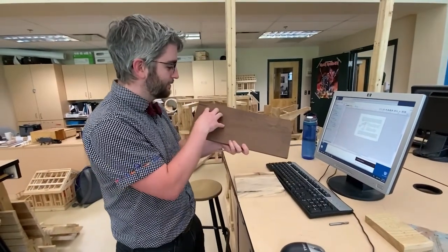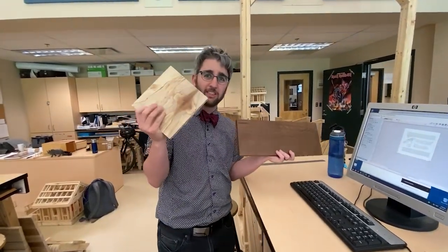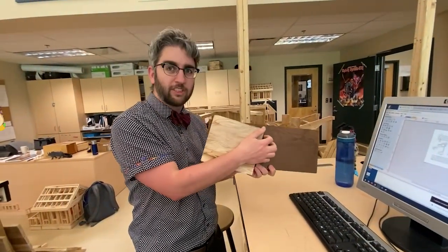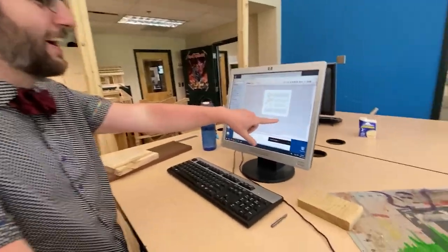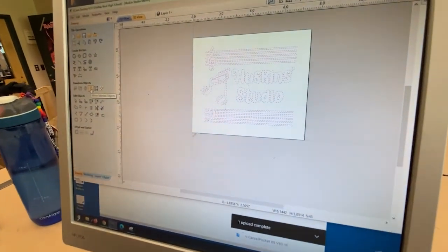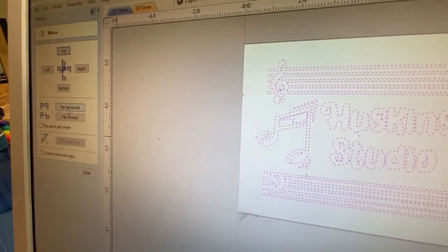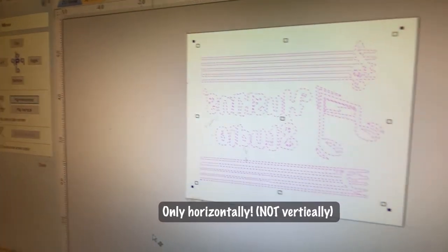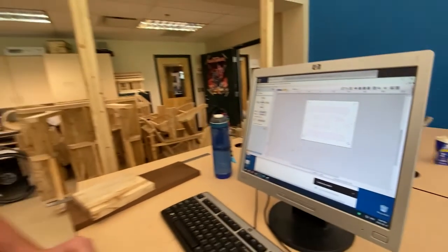All right, so we got our machine set up. It's going to be able to carve it in here, but now we need the mirror image on this piece so that they can sandwich together. So, sandwich. All right, here we go. I'm going to take my image, and I need to mirror it. So I'm going to click Mirror Selected Objects, and we're going to flip horizontally so that it creates that nice, beautiful mirror image pocket and can sit on top.